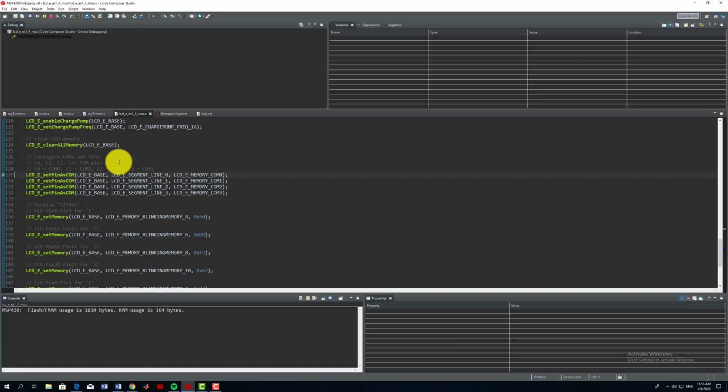So if we want them to appear on the screen individually, one by one, we can do it by run over or step over and introduce a breakpoint. So basically it's just very basic. It's just the fundamentals on how we make the data appear on the LCD screen. But if you want more, like if you want it to be blinking, we can introduce some different types of commands or functions into the screen.